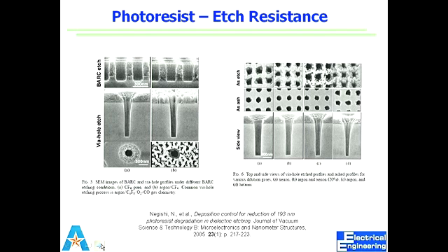And here we can probably live with it because it didn't do too much damage to the bulk, but at the interface, if we had silicon dioxide or some other material, that would have gone bad, because this could go through. It didn't etch the thickness uniformly, but it degraded that resist at many places.